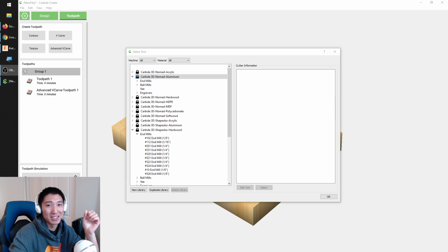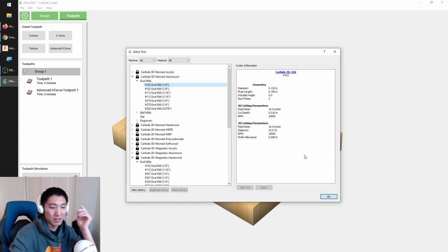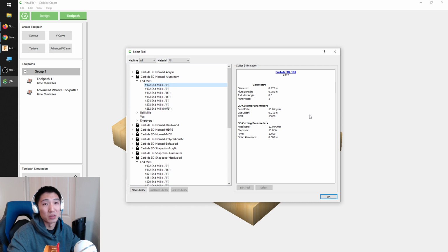If you're doing something like a 7000 series aluminum, that tends to be a tougher material. It's stronger. If you look at the material data sheet, it's about 30% stronger in all its mechanical properties. So you should probably back off on your depth of cut or your feed rate by 30% as well. Same with brass. Copper, it depends on your alloy. But it's basically just find a recipe that you know you can trust, and then work backwards from there and see, can I go a little faster than that, or do I have to go a little slower?